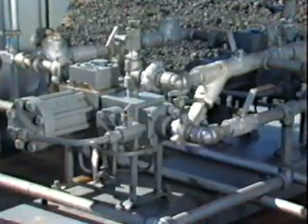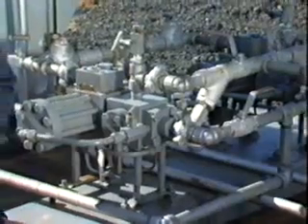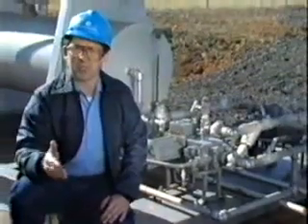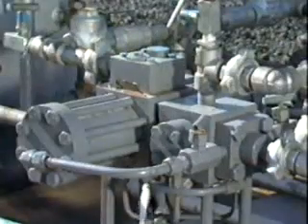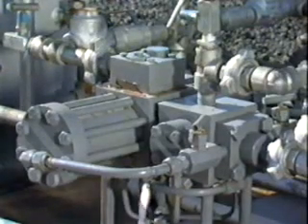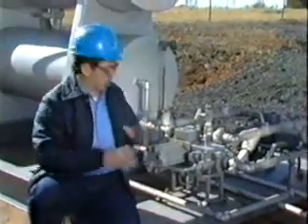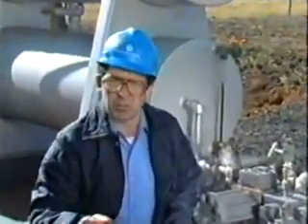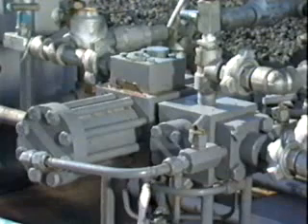Most small dehydration units use a fluid-driven pump, while larger units generally use electrical-driven reciprocating pumps. In either case, the pump is a critical part of the unit because it has the only moving parts in the system. Now, before the rich glycol enters the pump, it passes through a strainer to remove large particles. Leaks can be a problem around glycol circulation pumps. Proper packing gland maintenance and the use of the manufacturer's recommended packing can minimize this problem.